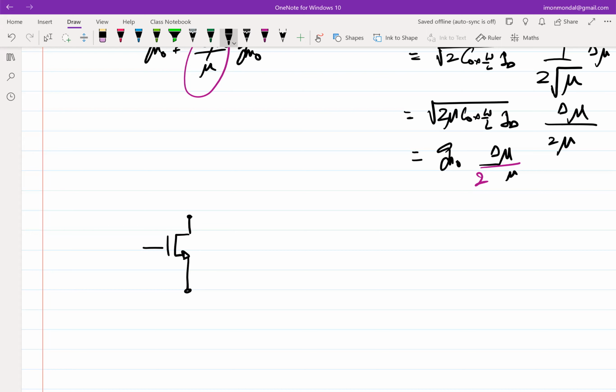You push current into the drain and affect the gate, right? So I can say that I can push current into the drain and then change the gate voltage. This is one way of biasing. In principle, this is what we saw, right? The one that we saw was this: we were pushing current into the drain and feeding the drain voltage to the gate.